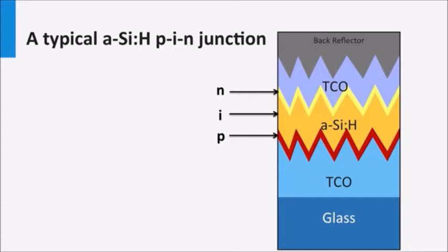P-doped layers are boron-doped amorphous silicon, but also the higher bandgap materials such as boron-doped silicon carbide and silicon oxide layers are used to enhance the transmission of the bluish light into the absorber layer. As back reflector, usually a TCO metal back reflector is integrated into the device. Metals are either aluminum or the more expensive silver, which has a higher back reflection compared to aluminum.